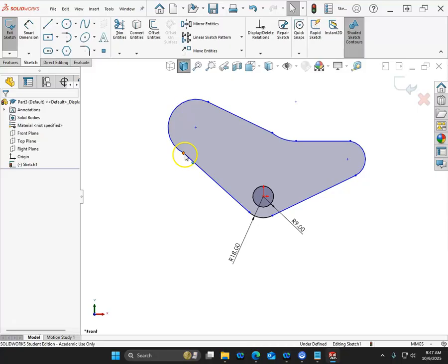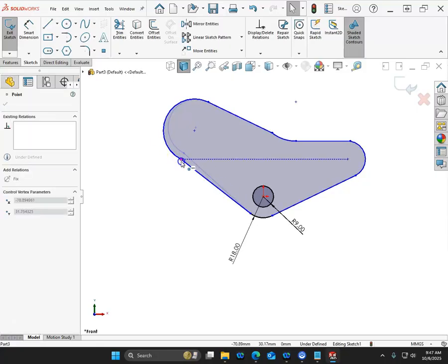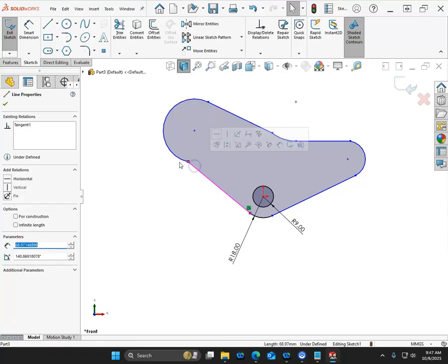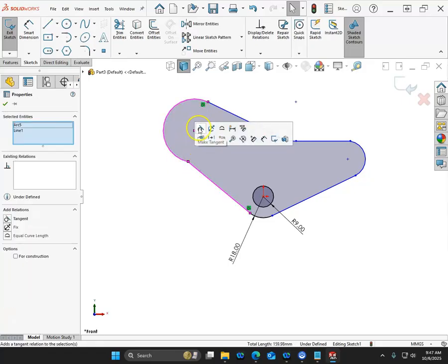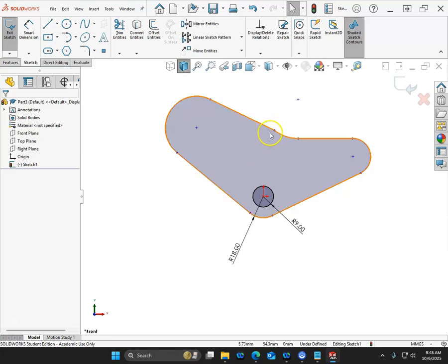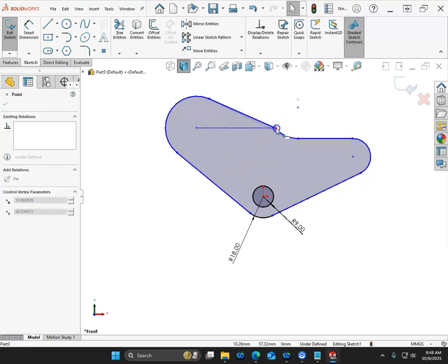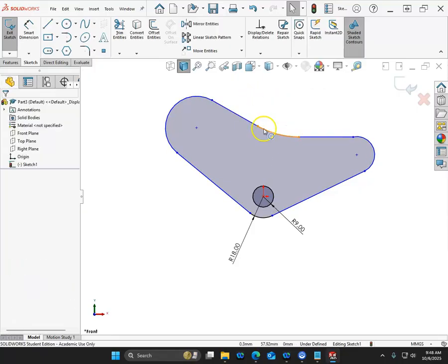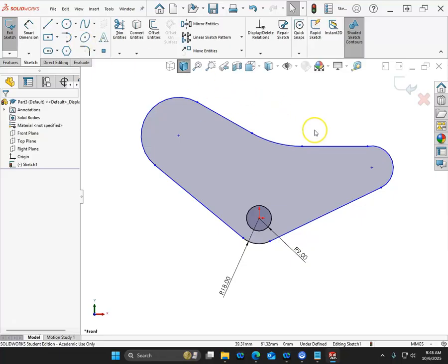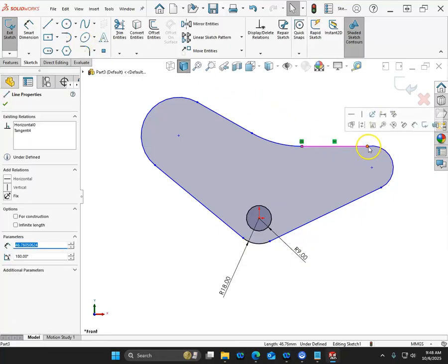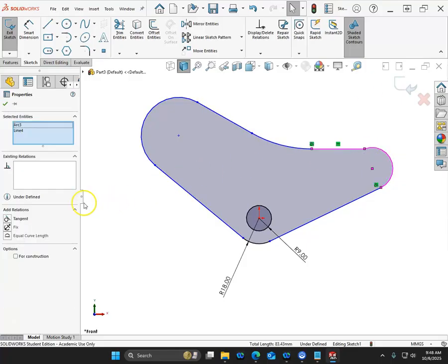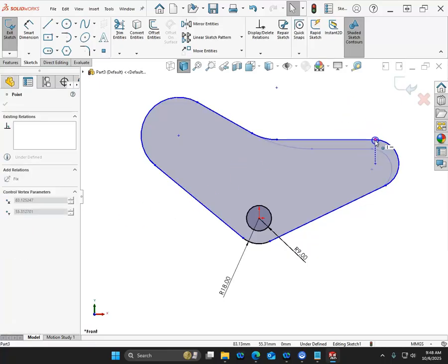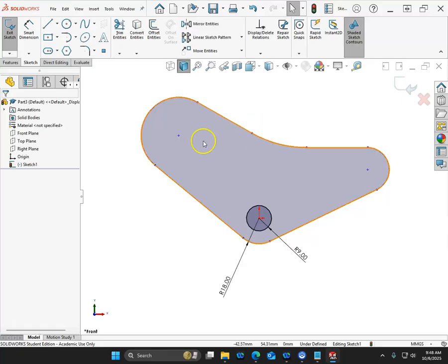And because it has that little step, I can tell that it's not tangential, so we select, control select, and then we'll go to tangent. Also there it has that little step and is going with something in the geometry. All right, one more right there. All right, so when in doubt, grab one of those endpoints, and as you drag it, if it does anything but stay tangent, you need a tangency. I don't know that there's a better way to say that.